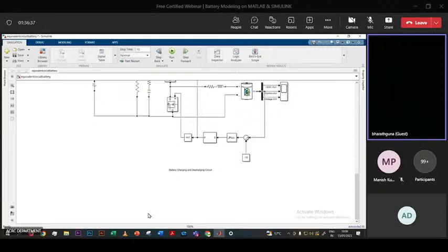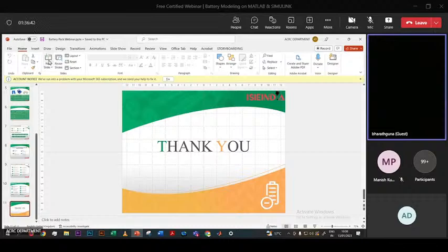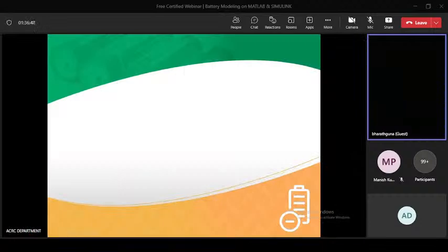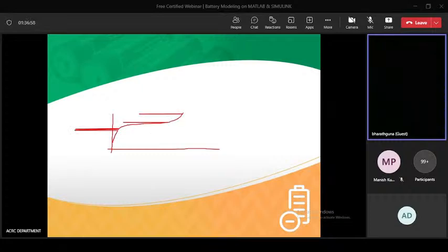Sir, 1 minute, I will give a clear explanation. First I am completely discharging the cell; the cell end voltage is 2.5 or 2.85. So when I completely discharge the cell, it comes to 2.5. Then I want to charge my cell up to 3.72. Once it reaches the voltage value of 3.72, the program will complete, like the cycle will complete.